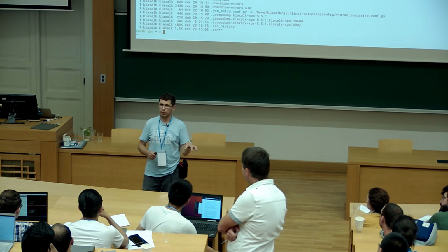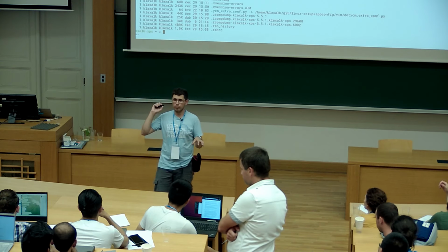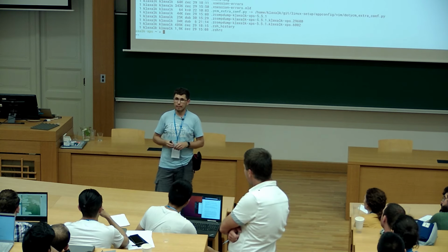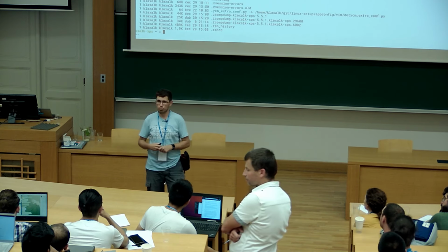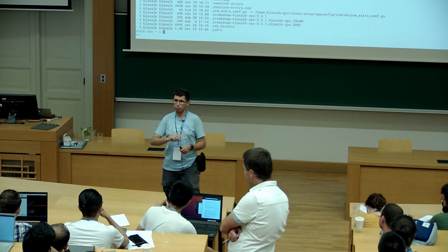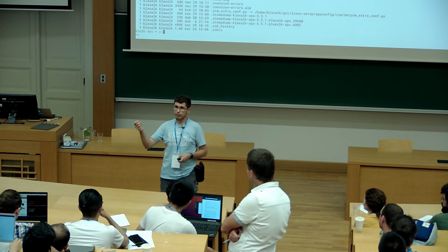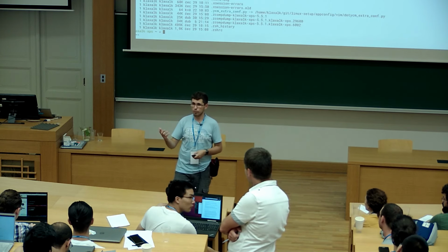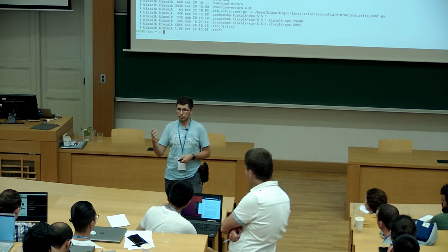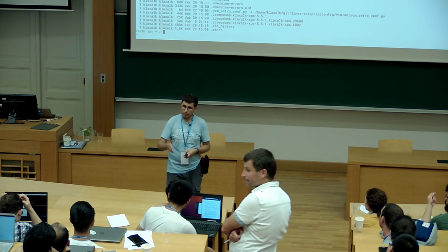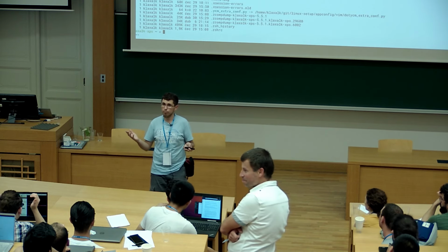Throughout the history, I first used a classical linear MPC, even without constraints. That was the video with the tricopter. Of course, that used a linearized model in near hover state, and it wouldn't handle aggressive maneuvers well. But nowadays, we have two instances of MPC which run on the drone. One is the so-called MPC tracker. That's the trajectory generator. It doesn't deal with the real rotational dynamics of the drone. It deals with the translational dynamics, up to the derivatives of the acceleration. So it works with aggressive maneuvers fine.